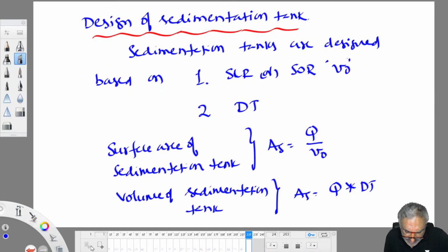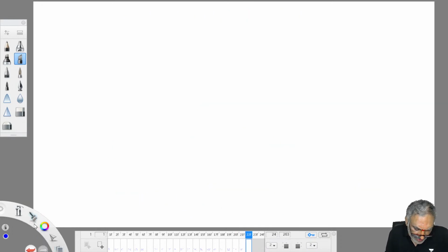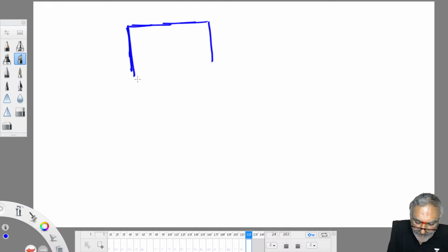Simple GATE questions they are asking related to only the thing is it captures flocculant particle. Plain sedimentation tank captures suspended particles. But capturing flocculant particle is much easier than capturing suspended particle. The reason being, flocculant particle keeps on changing its size, its mass and its specific gravity. Therefore, the trajectory of the particle movement is non-linear.